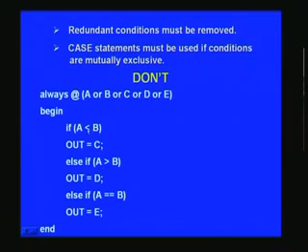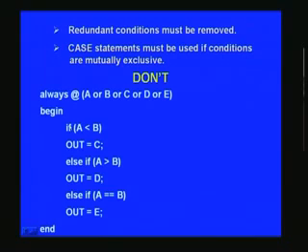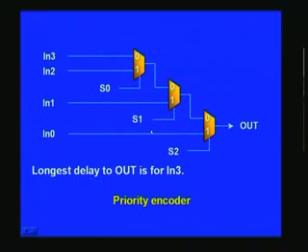So I'll tell you. See, A less than B: if this is not satisfied, it goes over here, then it implies that it is either equal to or greater. So this statement takes care of the next possibility, and what is left is only equal to here. So why do you want to put another condition here, which is already known? If you put this condition, what happens? It creates one more additional mux, as we have already seen. One mux for this if statement, then for the else if one more mux, and one more mux here, as we had seen earlier. Precisely the same thing.